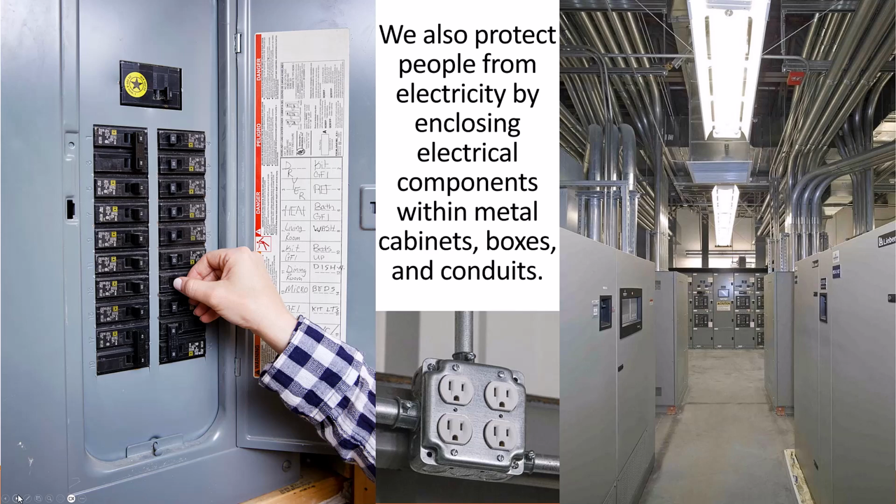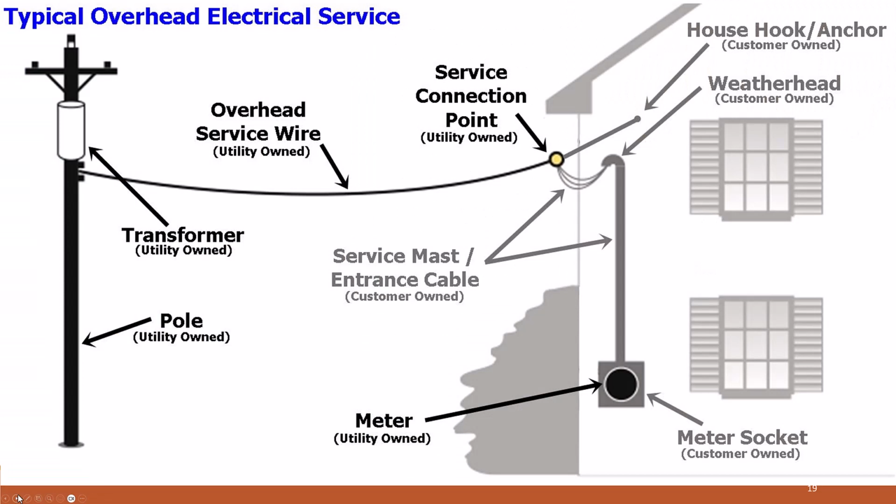So when you take the cover off, that starts to defeat that safety protection. These cabinets in this mechanical room over here on the right-hand side, we put the wires in metal conduit in industrial facilities and such, and in commercial places many times too. And metal electrical boxes and conduits shield you from that electrical field. So we also keep the wires up high.